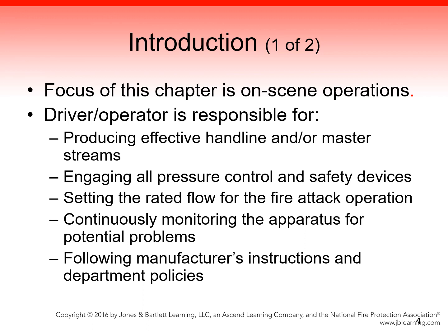of an emergency. This includes operating the fire pump and other fixed systems and equipment that are mounted to the fire apparatus. While operating the fire pump, the driver-operator is responsible for producing effective hand line or master streams, engaging all pressure control and safety devices, setting the related flow for the fire attack operation, and continuously monitoring the apparatus for potential problems.